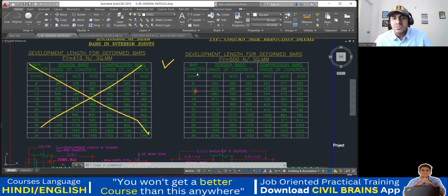Now he's telling us, if you're using a diameter of 8, 10, 12, 16, 18 (18 is not available, but still they have written it), 20, 22, 25, 28, 32, 36, and the grade of concrete is M20, then if you're putting up a 12 mm diameter bar, you need to give a development length of 680. Got it? Suppose it is a tension bar. Suppose it is a compression bar, for a 12 mm diameter bar, for M20, you need to provide 544.